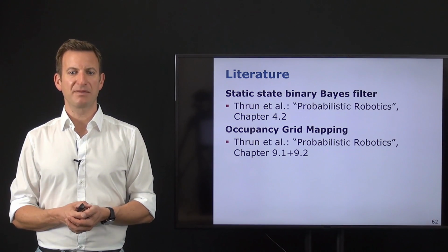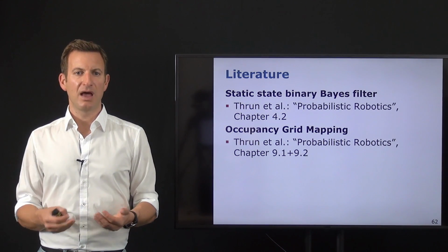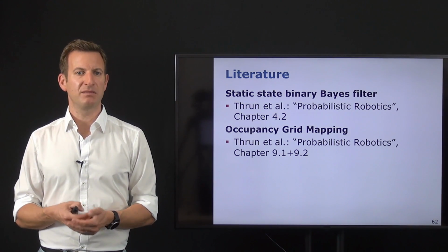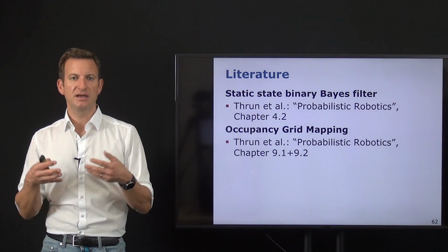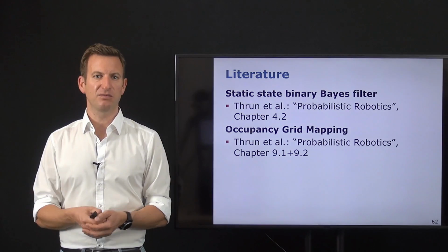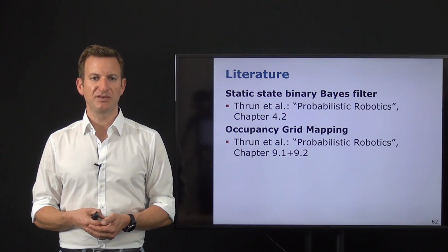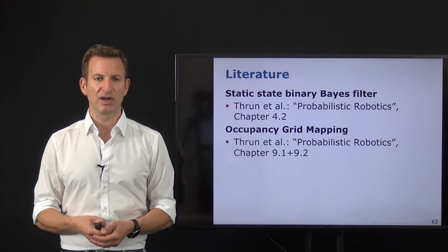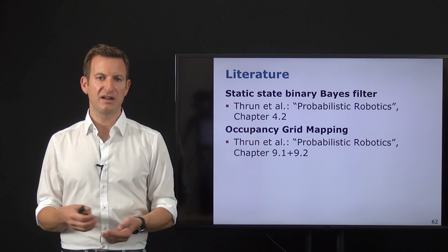With this, I'm coming to the end of this lecture, and I hope you have learned today how you can build a map, a floor-plan-like map of the environment. If you have a range scanner, you can treat all the cells individually and estimate for every cell if it's more likely to be occupied or free, which then turns into a probabilistic representation, if you do this in a correct way, telling the probability that a cell is occupied or that it is free.